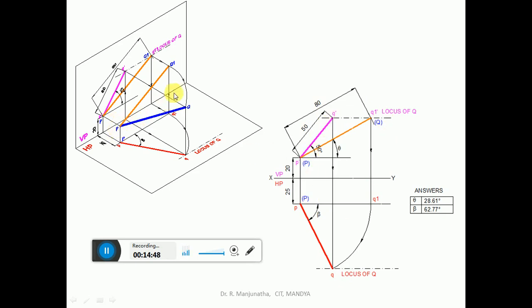That is what we have done here. First we projected this point directly and then rotated. In space you take P and Q1, then rotate it such that this q is on this end projector here. So this point becomes small q. When you look from the top view, this line when projected gives this point, which is q. Then join pq with a dark line, and you have the locus of q. This is how we analyze the first step.